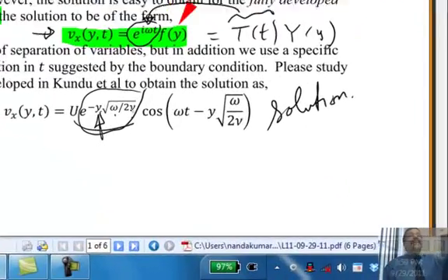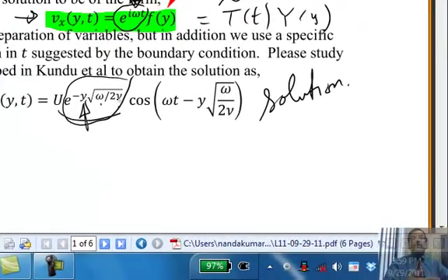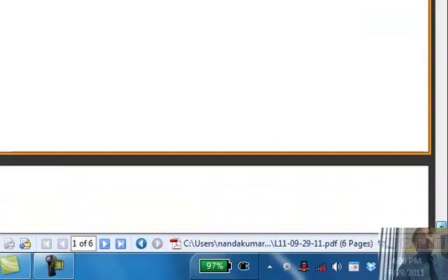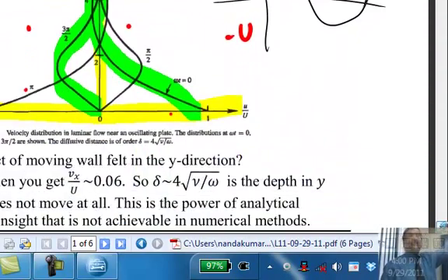So any dot that you put in will start moving in the forward direction, and then it reaches the maximum velocity u, starts going back, and so all the fluid will start retracting. Okay, so every dot that you place on that fluid element will traverse only in this direction, back and forth. And as you go farther and farther away, the extent of the amplitude will become smaller and smaller.